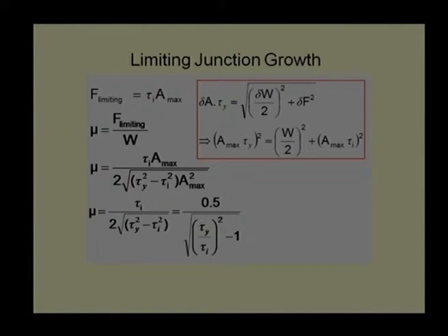If the interface is fractured at the value of the shear strength of the material, then the coefficient of friction will be very, very high. However, if the shear strength of the interface is very low, the coefficient of friction will be lower, and this is the reason why we provide lubricant. If we provide lubricant at the interface, the shear strength of the interface will be almost negligible compared to the solid material strength. Just to get a feel of that, we did some calculations.